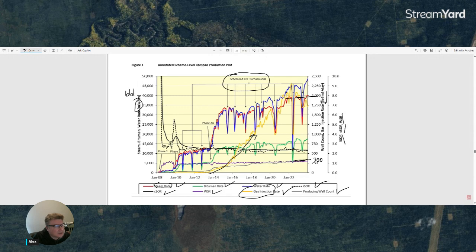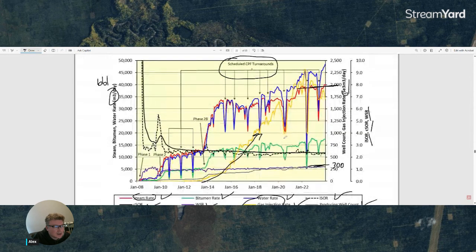We want to understand the injection of the yellow line, which is NCG co-injection with the steam. By the way, what's interesting here is that you can see a kind of plateau of steam injection rate as the NCG injection rate increases, and then we see this behavior in oil production rates. Then you get another leg of steam injection rates and oil production uplift because of the heat transfer, but that also correlates with gas injection rates in yellow, which is also intriguing.